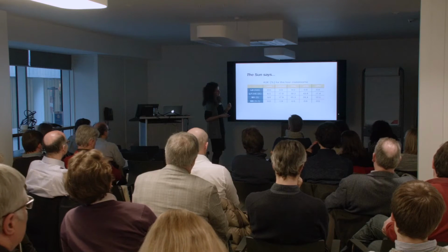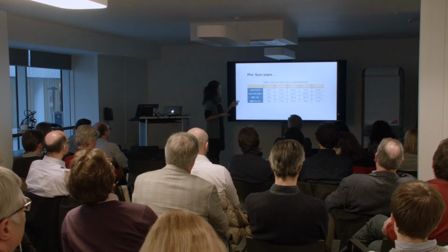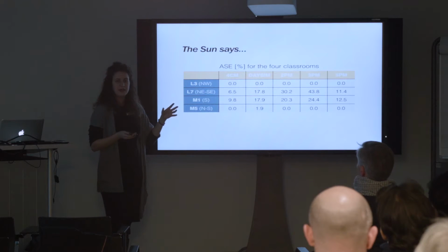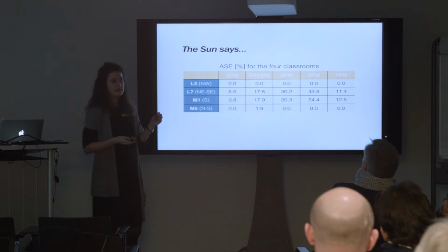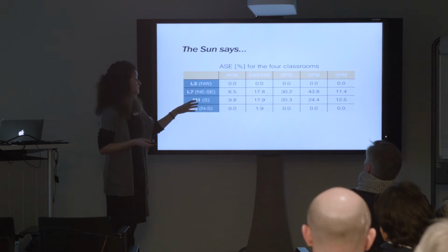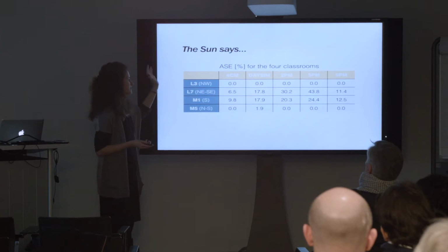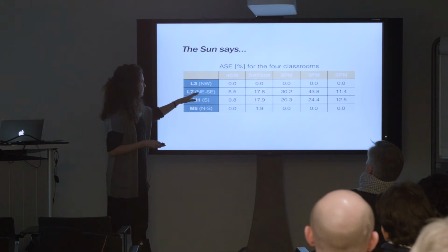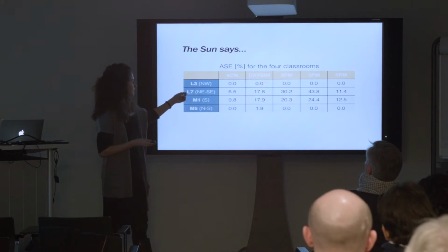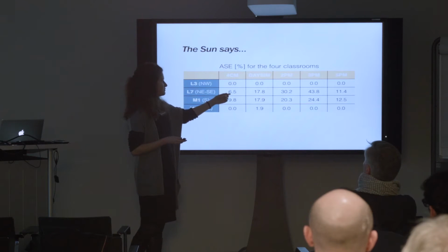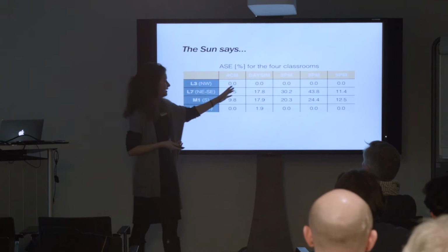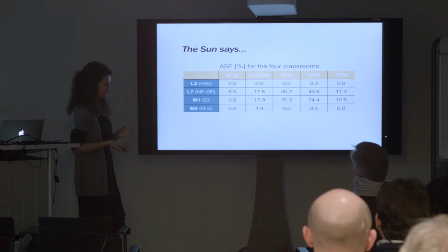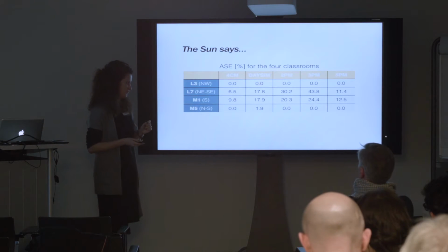Anyway, after you do all this modification, you get some results from them, and these results are not really agreeing with each other at all. For the annual sunlight exposure, because each method uses a different way of handling the sunlight part, you get very different results. If it's northwest directed, you don't get any direct sunlight for that time and that value. But for example, for this room, we get a minimum of 6.5% for the four-component method and a maximum of 43 for the three-phase method. So given that it's requiring some regulation, one has to be careful about this metric.